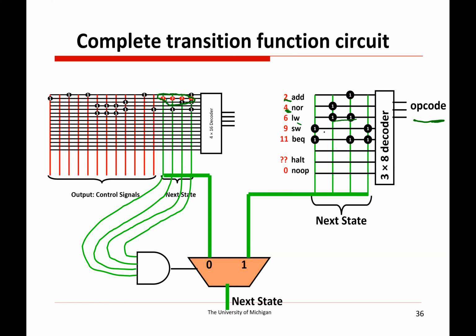And then we just need to figure out whether we're supposed to use this next state logic or this next state logic. So one trick that I'm going to do is put all these question marks, let's just set these all equal to 1. We can do that because we didn't use all the possible states that we could. We only have 13 states, so this basically corresponds to the 16th state. That way, if we ever read out all ones for the next state, we know that can't be an actual next state because there is no state 1, 1, 1, 1.